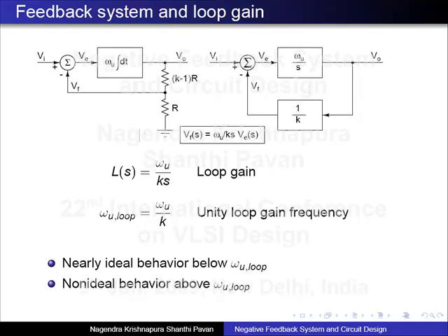See, right now we are discussing it at the block diagram level where there is no loading. So we'll later see what to do. We can discuss what happens with loading and so on. It's not easy to break the loop, but this is a conceptual breaking of the loop that we do for analysis. If you make a transistor level circuit and break the loop, many things can happen. The loading will change and the bias will change. You have to take care of both.